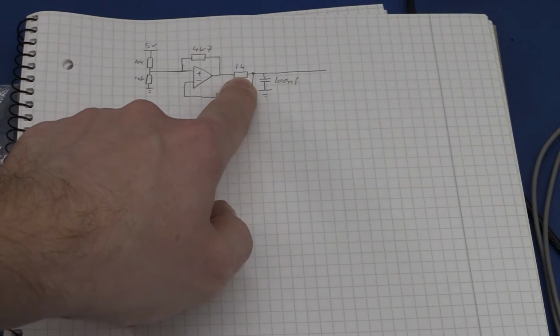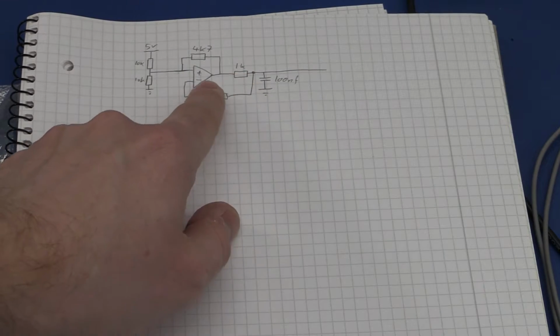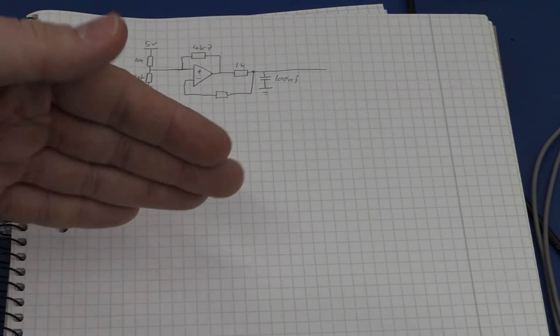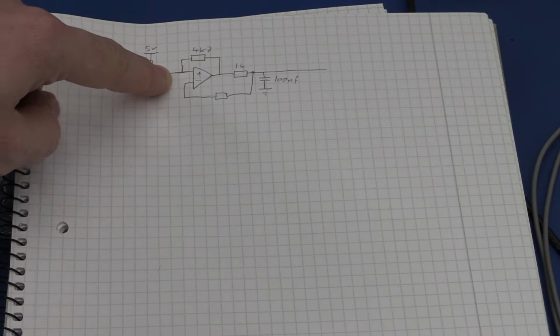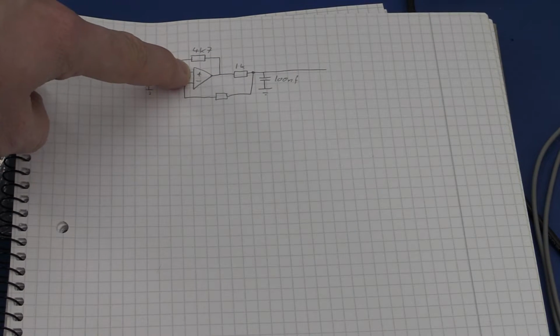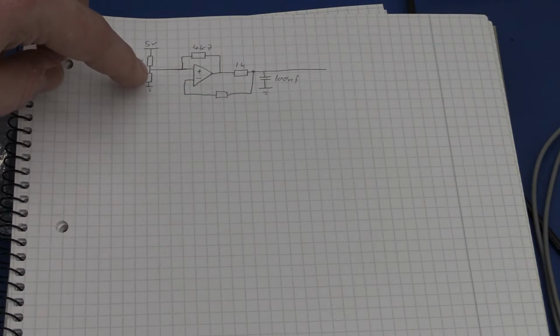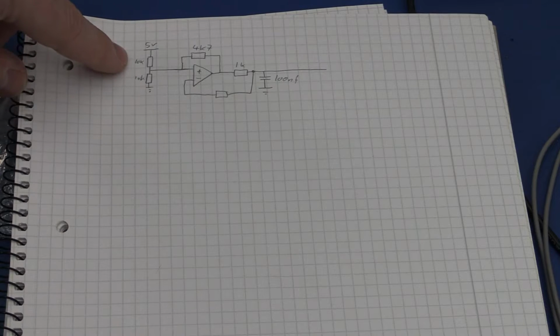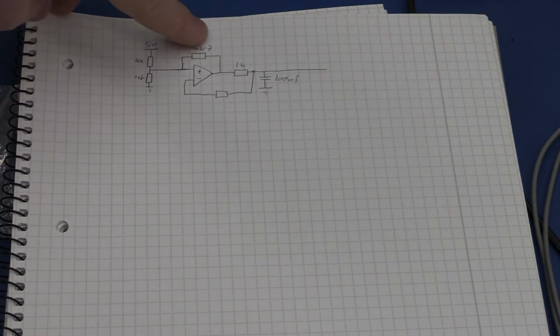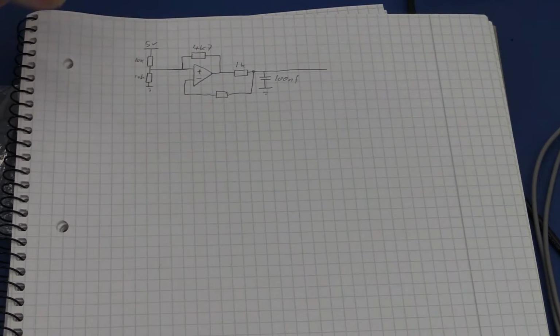It can do that because we have a resistor here, so the output can jump to the high rail or the low rail. It will then affect the input voltage on the non-inverting input, setting it to some voltage, which would be the divider here with 10K parallel to 4.7K to either of the rail, depending on where it decides to go.